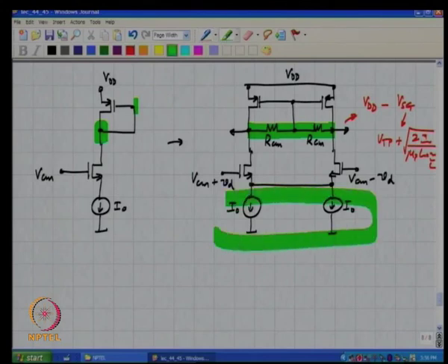And again, the control, as we discussed before, we assumed that these two are independent and the load currents are dependent. One can reverse the situation and say the load currents are independent, and I am going to tweak the tail current to make sure that the common mode at the drains of the two input transistors remains fixed. Okay. So, there are any number of ways of making this work. All right.